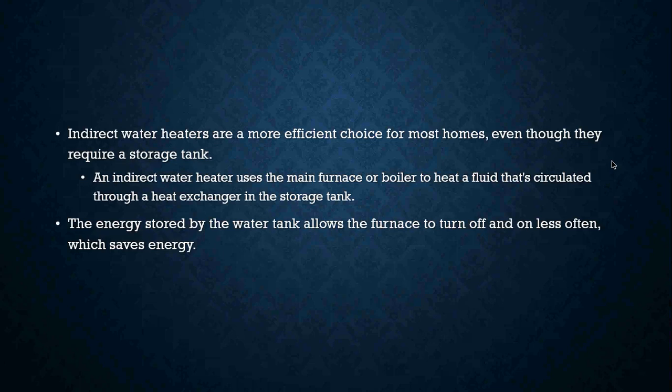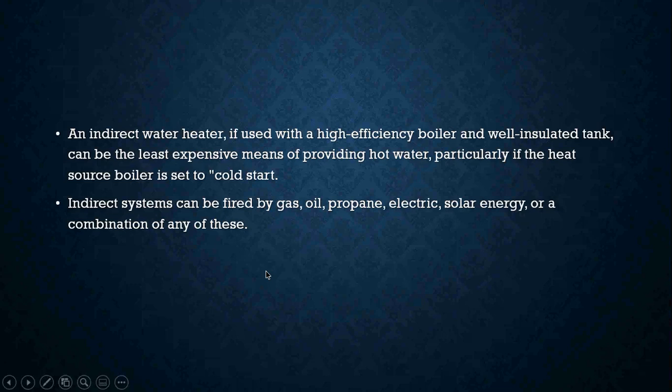The energy stored in the water tank allows the furnace to turn off and on less often, which will obviously have energy savings. An indirect water heater, if used with a high-efficiency boiler and a well-insulated tank, can be the least expensive means of providing hot water, particularly if the heat source boiler is set for a cold start. Okay, indirect systems can be fired by gas, oil, propane, electric. We can use solar energy or a combination of any one of these.